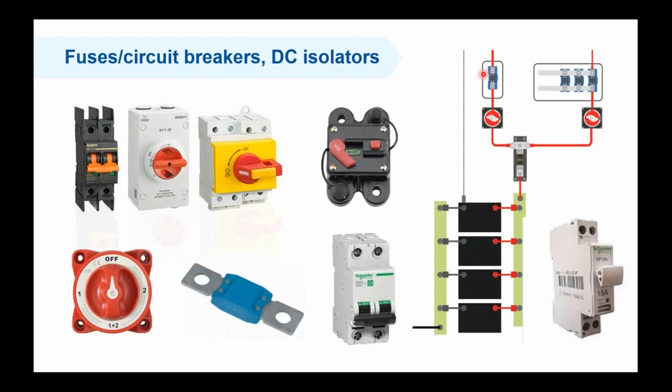A device might withstand the high current for a longer time, but cables get heated when there is a high current. And then when they heat up, they can start a fire, and it's a disaster. So fuses need to protect the cables.